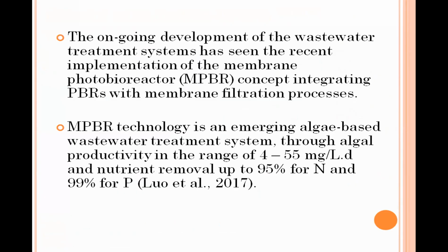So we think to develop more and more the researchers' enthusiasm to create the membrane photobioreactor. The ongoing development of the wastewater treatment system has seen the recent implementation of the membrane photobioreactor concept, integrating photobioreactors with membrane filtration processes. The membrane photobioreactor technology is an emerging algae-based wastewater treatment system, with algal productivity in the range of 4 to 55 milligrams per liter per day, and nutrient removal up to 95% for nitrogen and 99% for phosphorus.